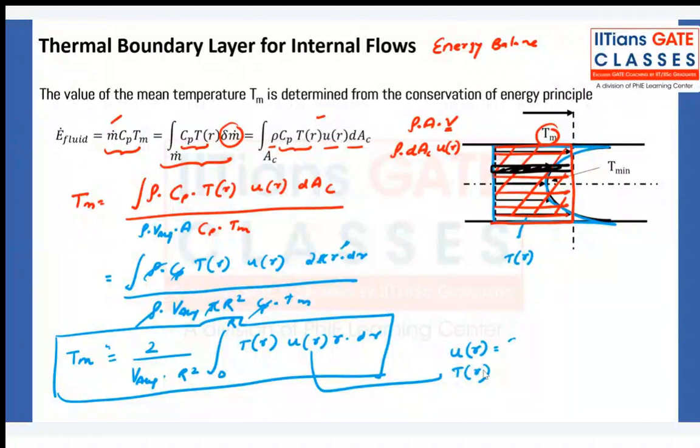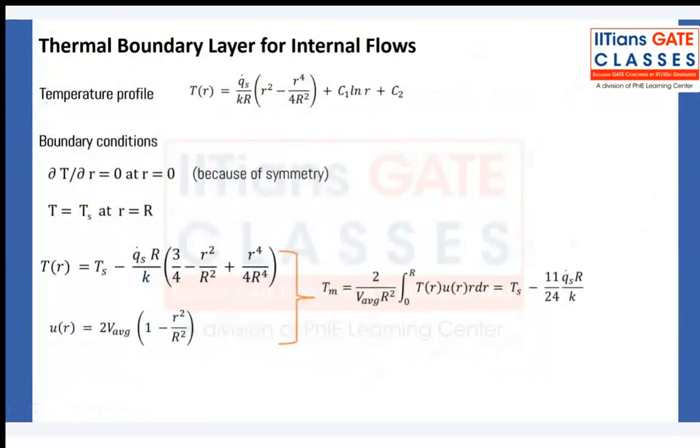So temperature profile, again we will do the same. We will solve our continuity, momentum and energy equation, and I can define my temperature equation, how my temperature is changing with respect to R. But again, we have C1 and C2 as constants. I need two boundary conditions to calculate this T(R).